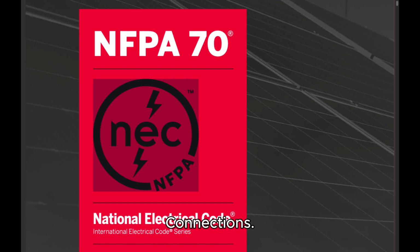110.14 Electrical connections. Because of different characteristics of dissimilar metals, devices such as pressure terminals or pressure splicing connectors and soldering lugs shall be identified for the material of the conductor and shall be properly installed and used. Conductors of dissimilar metals shall not be intermixed in a terminal or splicing connector where physical contact occurs between dissimilar conductors, such as copper and aluminum, copper and copper-clad aluminum, or aluminum and copper-clad aluminum, unless the device is identified for the purpose and conditions of use.